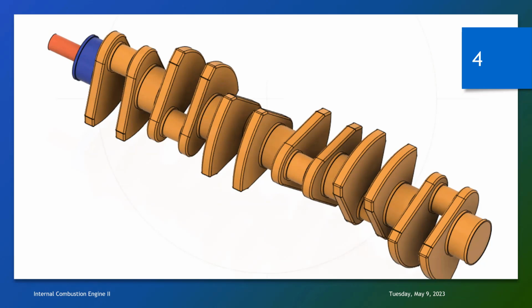The crankshaft is like this because each cylinder has to be oriented. For instance, if it is 720 degrees, each one will be at 180 degrees to each other, depending on the time of fire. So that is why you have all these orientations. If they are all oriented in the same way, it would not be a possible working engine. It cannot work. It has to be arranged with a specific firing order that will give you a smooth ride. So this is just how one might look.